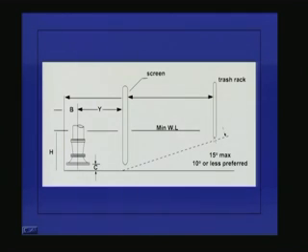At the entry to the pump sump, we need to have a trash rack to eliminate large debris. Then we have this screen here, which will kill a lot of flow disturbances, and the water will be approaching the pump more or less uniformly. This screen has to be there, and we need to have enough depth of flow near the pump,